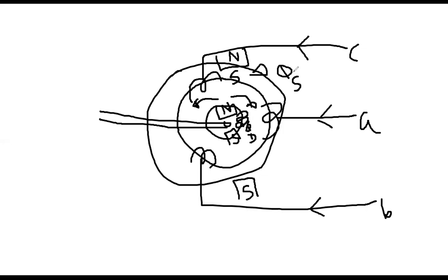So there will be interaction between phi s and phi d, and then the torque will be produced, and the rotor will start moving. And then at some point, because this is also moving, when the South Pole comes near the North Pole, it will be attracted because it is the opposite pole, and then it will be locked and synchronized and it will start rotating permanently. That's why, with the help of the damper winding, the synchronous motor gains speed.